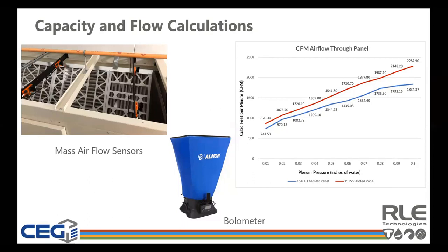At the contained aisle level, and I'll explain a little caveat around this at the end, you can use 156 to 160 cubic feet per minute (CFM) per kilowatt of IT load as a rough rule of thumb. So here's the caveat.